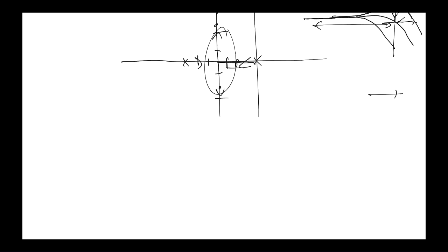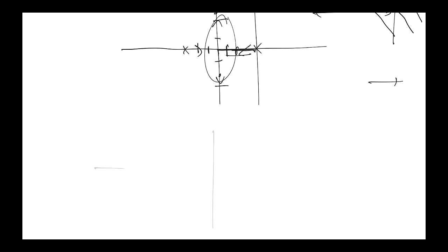Because the phase margin, if we look at a Nyquist plot, is telling you how close you are to the critical point -1, in terms of the angle of the open loop transfer function at the crossover frequency. That's why I've drawn a circle of radius 1 here. So that's the little vector that tells you what the open loop transfer function is at the crossover frequency, where it has a gain of 1.